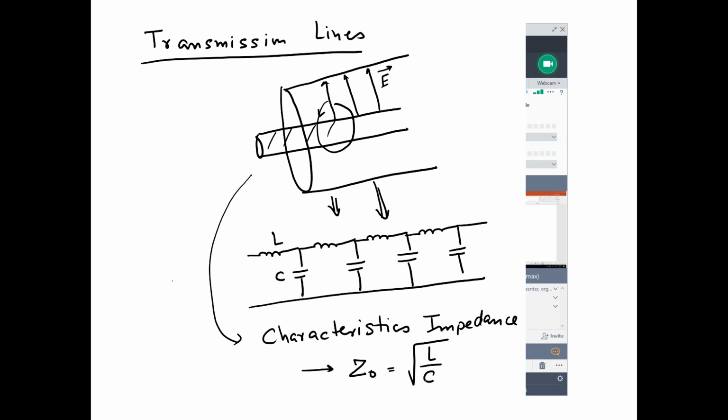And then you looked at what happens if I have two different transmission lines of two different Z naughts. What kind of reflections do I get? How do I correct for those reflections? How can I match different loads on these transmission lines? And that works very well in the discrete circuit world, or in the low speeds. And when I say low speeds, I mean few gigahertz. That works pretty well in that case.